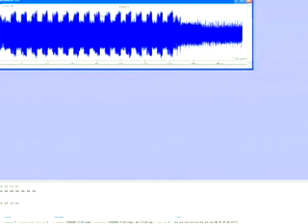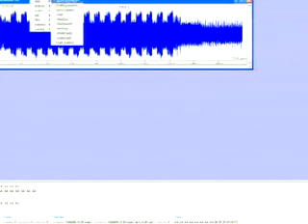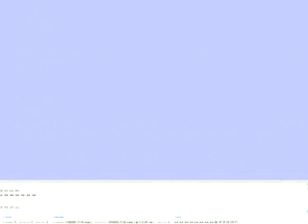So now we have a version that inserts randoms all places through the DES operation, and still with the same input data. So there's no difference. Any variation you see is not from the input data and not from the key.